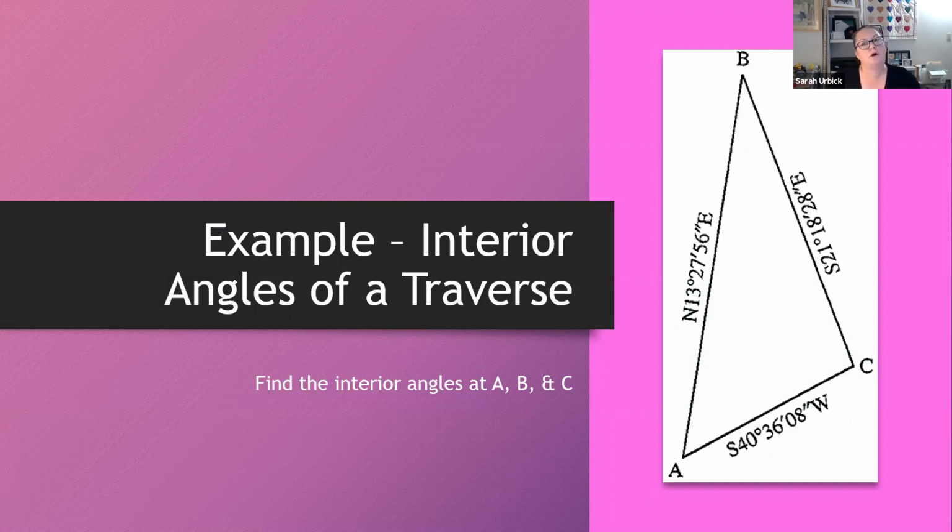All right, so here's the thing. Before anybody goes out and digs more than 6 inches down into the ground, we are supposed to call in a utility location request.